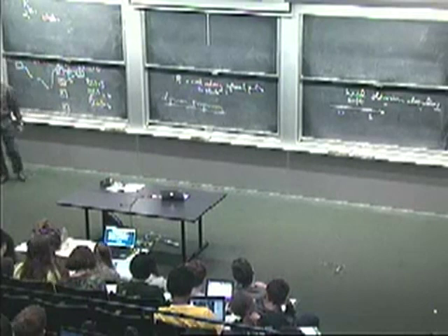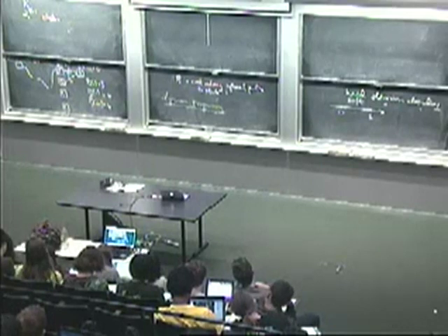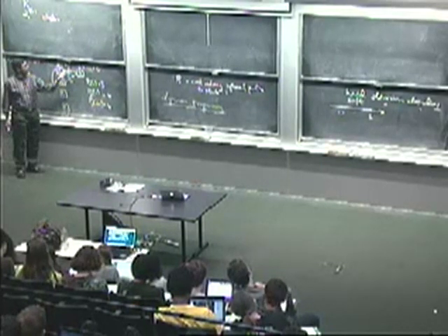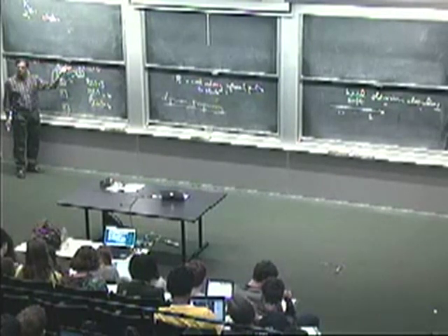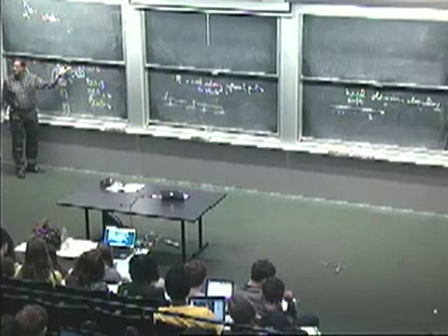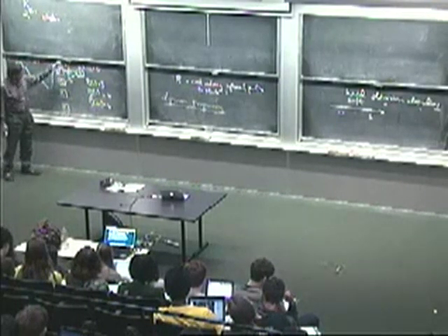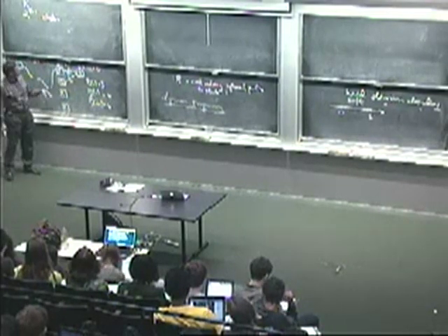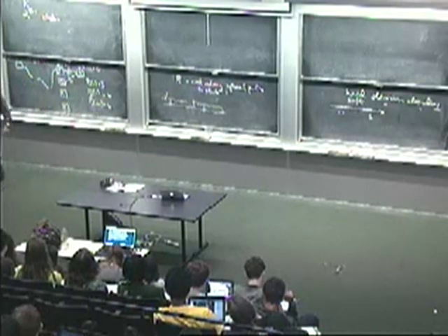It's the piece contributed by the branch. This is the notation we've used. We've already talked about this, that you could either do a hard decision kind of rule where you've already set these to ones and zeros, or you could stick with the original samples. If you've already converted them to ones and zeros, there's a natural notion of distance, which is the Hamming distance. And there's a probabilistic reason why you would want to do that. So we're sticking to the Hamming distance setting right now, so hard decision decoding.